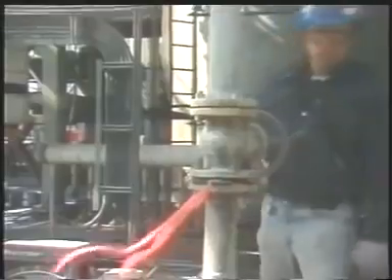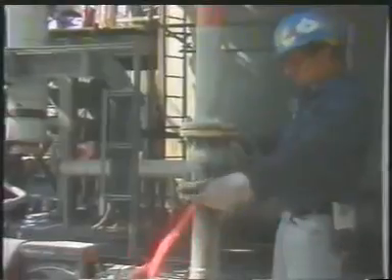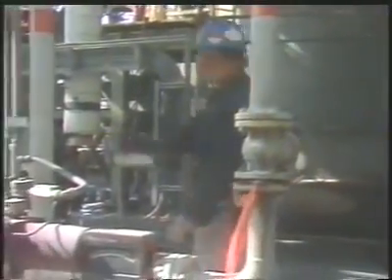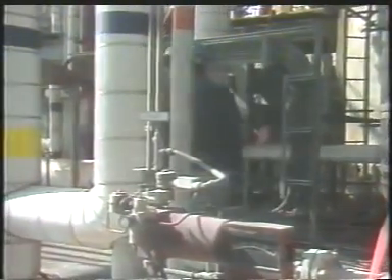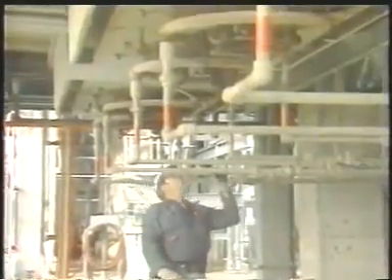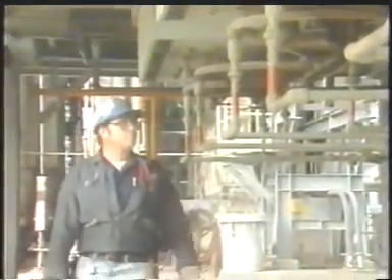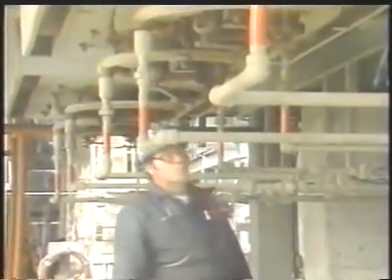The first step in the pre-startup inspection is to check that the pilot and main fuel systems are blinded and that the fuel supply for each burner is closed. Then inspect the furnace to assure that it is ready for startup. This involves inspecting the furnace to make sure it's clear of debris, checking the burners, and making sure all the furnace doors are closed.